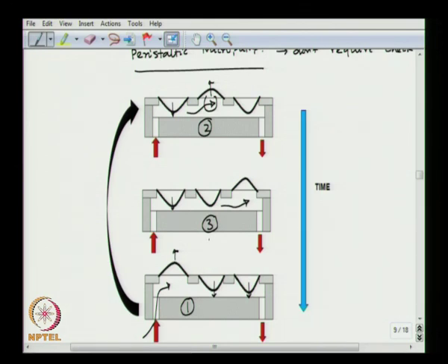Then it goes back to the first cycle, and the liquid present here exits when that membrane goes down in the third cycle. At the same time, liquid comes in through the inlet because this chamber is moving up. So, the motion of the different membranes occurs sequentially in a controlled manner to drive the fluid from the inlet to the outlet using peristaltic motion.